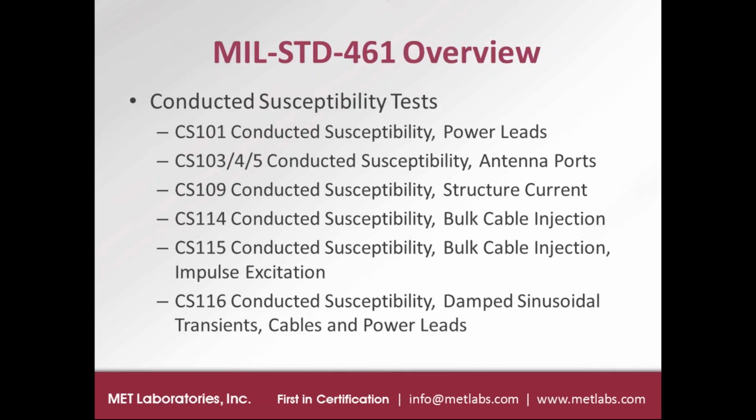So when they talk about conducted susceptibility, that means we're going to generate a disturbance in the lab using equipment to simulate disturbances which would occur on the platform where the equipment is expected to be installed. And we're going to inject those disturbances in a conducted fashion into the external cable bundles of the equipment under test. Most of these tests do that by using inductive probes which couple the energy onto the equipment under test cables. There are a few of the tests that do it using a transformer.